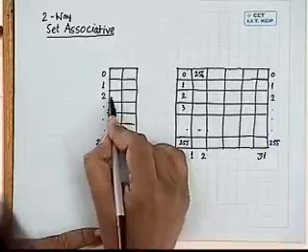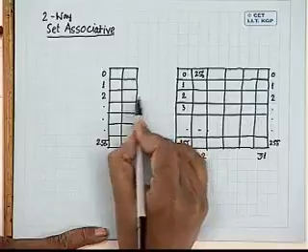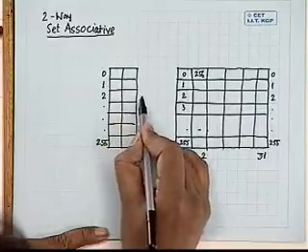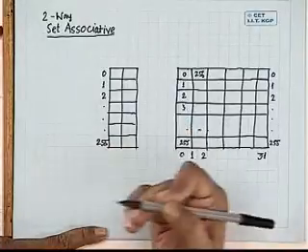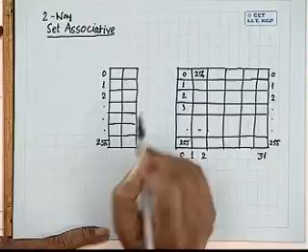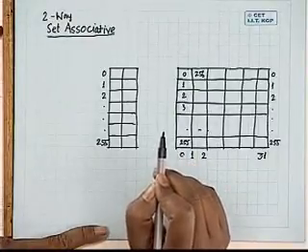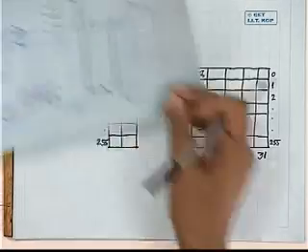Okay, I can increase the number of cache lines, or I can increase the cardinality of this set. Instead of having 2, I can have 3, 4, 5, and so on. So the more cache lines you put in a particular set, the more the number of cache misses will go on reducing, but at the cost of the number of comparators. In the earlier case, for direct mapped cache, I had only one comparator.